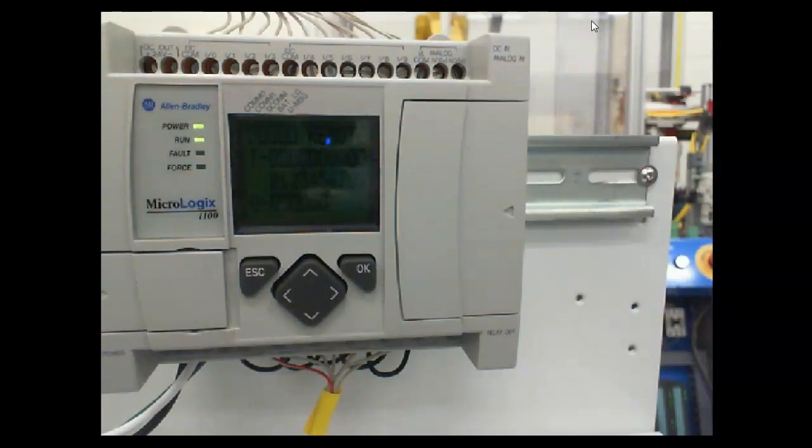It protects you against electrical shock and then arc flash, which is when we have a high energy short circuit. It creates a flash that's hotter than the sun that causes things to melt. NFPA has identified 70 volts as the lethal voltage level. So as soon as you get above 70 volts, you've got to start wearing special PPE. Now PPE, I used to have to tell everybody what PPE stands for, but since COVID came out, everybody knows now that PPE stands for personal protective equipment.